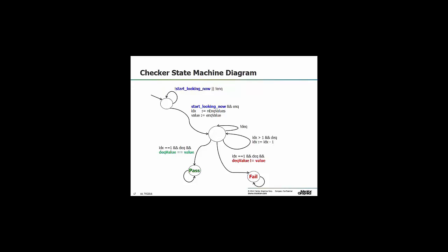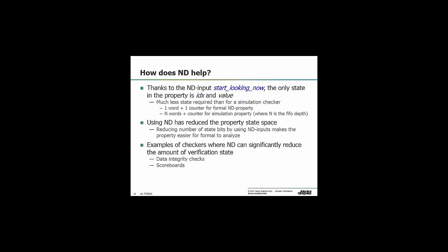So actually, I want to say that this is exactly what I said about this way to debug the FIFO. You can write it using what we call non-deterministic inputs, something that you cannot do with simulation. This saves you a lot of states in the verification.